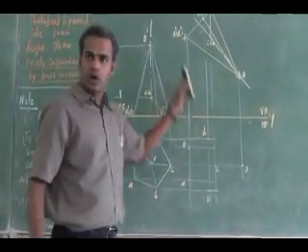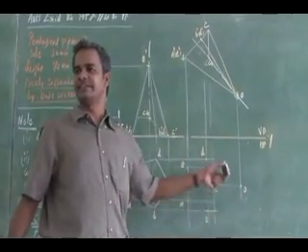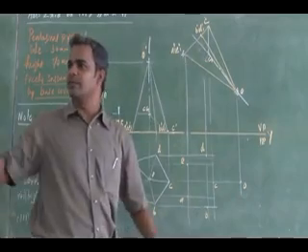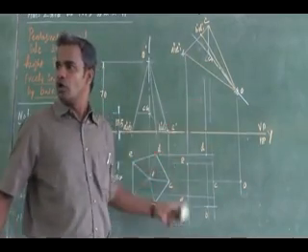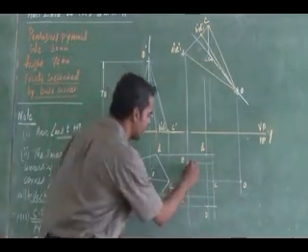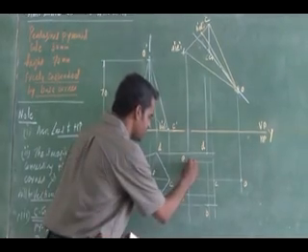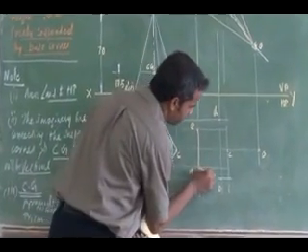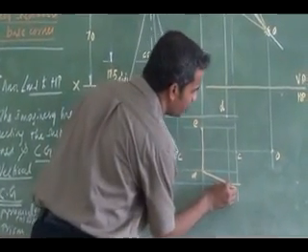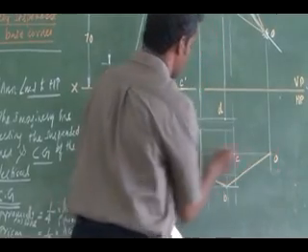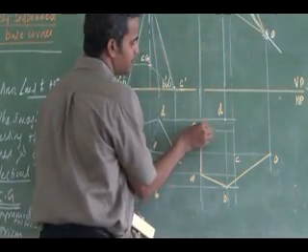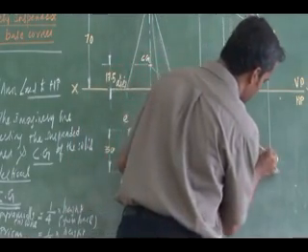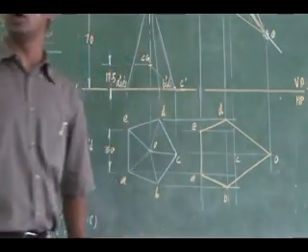Right. Now you have to show the visible and hidden edges. As per the note, first of all I have to finish the boundary. The boundary you have to join as a visible line. See here, the boundary is A to E. A B is the boundary. Then B O. Then E D. So this is the boundary I have joined.